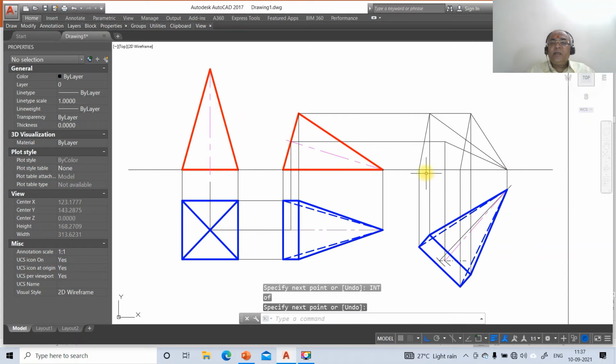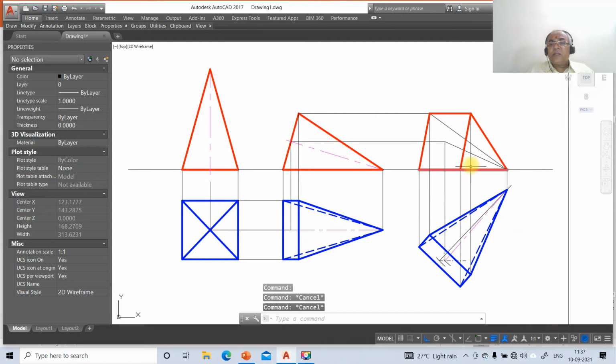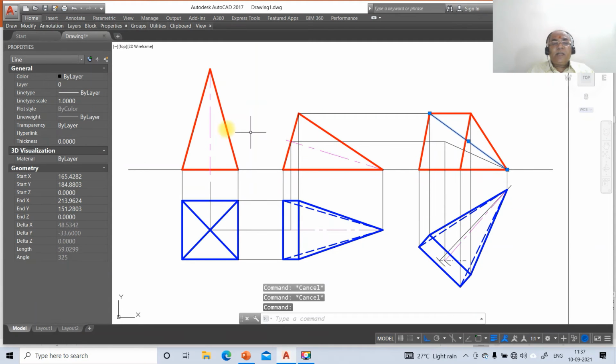Now we have all the criteria. So all the exterior edges of the boundaries of the solids are visible, and when you look from the front view, this entire surface is visible. So obviously these two lines will be visible. Then go to layer, take the layer as front view, then you just click over this, click this as front view hidden and take the dimension as 15.